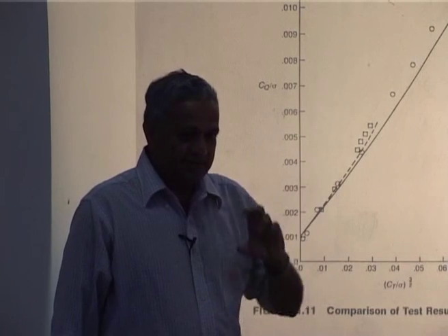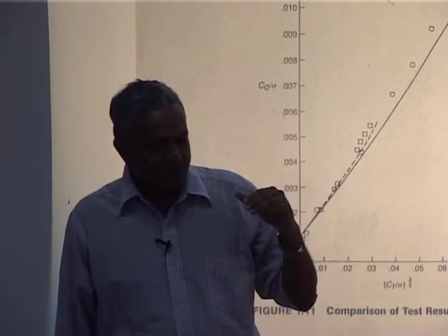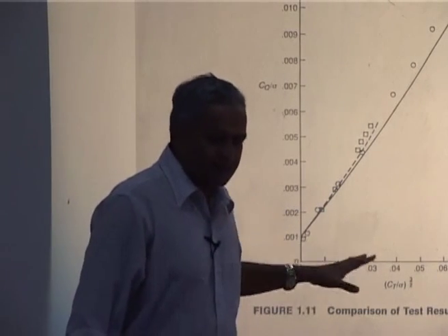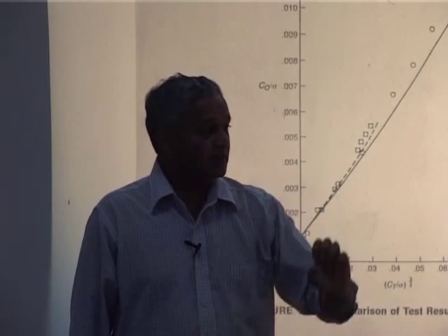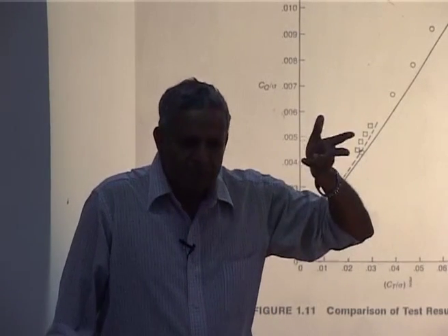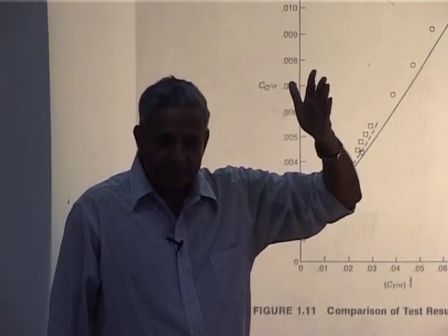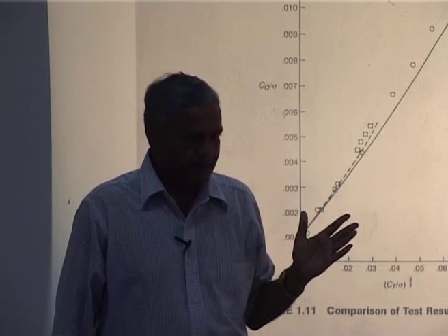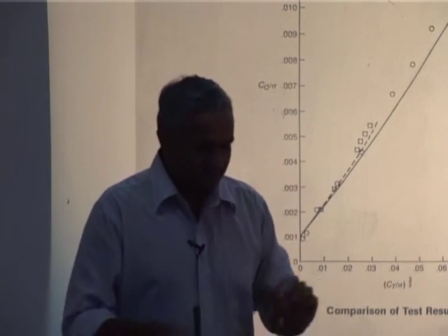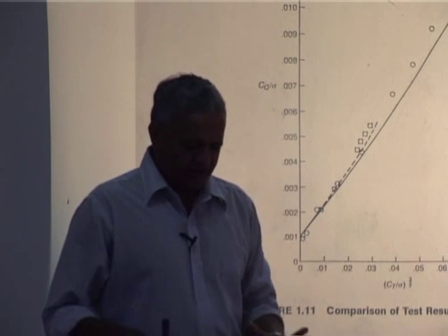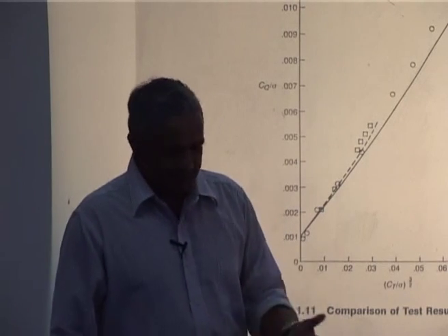But CT by sigma, that is why CT by sigma, last class also, has so many meanings. In the hover case, you know that it is approximately the pitch angle. Now, if CT by sigma keeps on increasing, that means what? The mean pitch angle you are increasing. Mean pitch angle increase means you can increase up to some point, after that the blade is going to stall. That means you can go up to that CT. Suppose you design a helicopter, you do not design only for that particular weight, even though you design for 4000 kg, sometimes you may have to carry a little more, the capability.